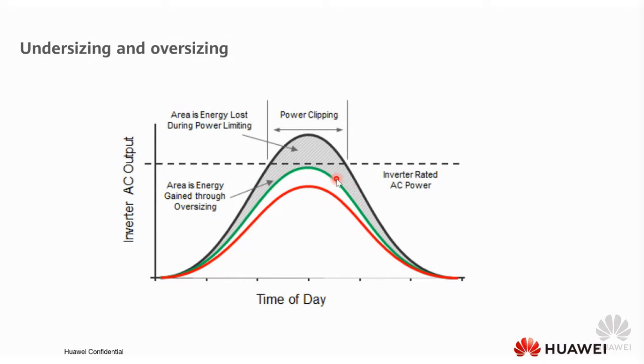And not only this. There will be some cases, for example in autumn or during the fall, where even with a DC-AC ratio of 1 you would get this curve, because at that season there will be no extra power available from the DC side. But if you have an oversized DC-AC ratio, you will have this power. There will be no clipping, no so-called losses on the inverter.